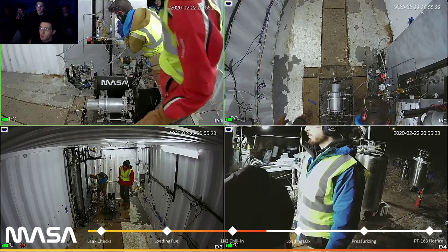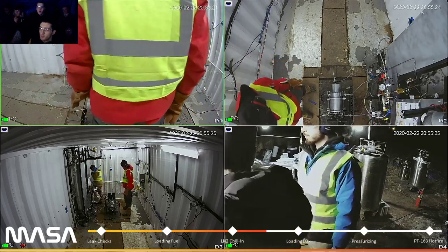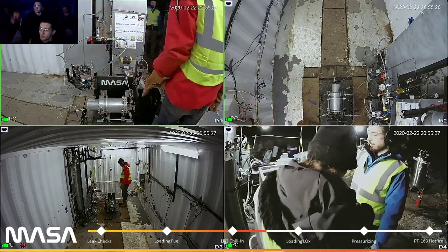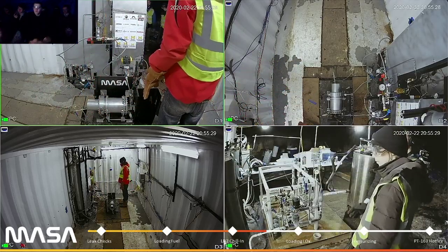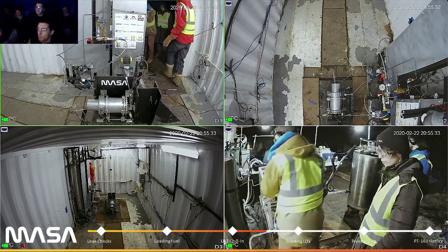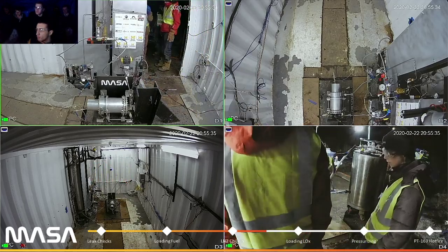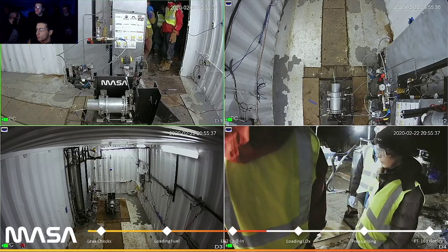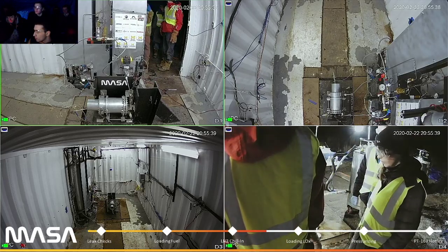We actually don't have many cryo pressure transducers. What we do is we have a standard pressure transducer that has a very long standoff tube that insulates it from the low temperatures, but it still gets the same pressure. So we don't really have any cryo transducers. LOX purge for 3 seconds.